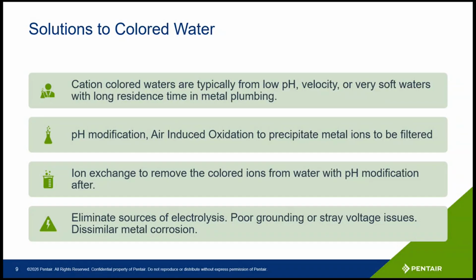If it's not from the water, where is it from? If you detect stray voltage, this is where having a multimeter and knowing how to use one has benefits in water treatment. Make sure your equipment's grounded. If you've installed a plastic valve head into copper plumbing and it's part of the ground system of the home, make sure you bond those copper pipes together so you have a good earth ground. That alone could create this sort of situation, and it's a good thing to check when dealing with potential corrosion issues due to electrolysis.